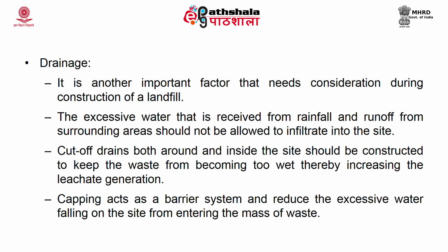Cut off drains both around and inside the site should be constructed to keep the waste from becoming too wet, thereby increasing the leachate generation. Also, the capping system, the final cover which acts as a barrier system, will prevent the waste from coming into contact with the rainfall, and it will also prevent the rainwater from entering into the waste.